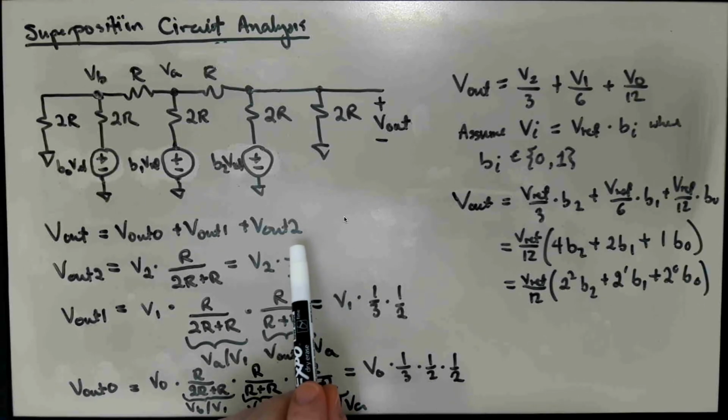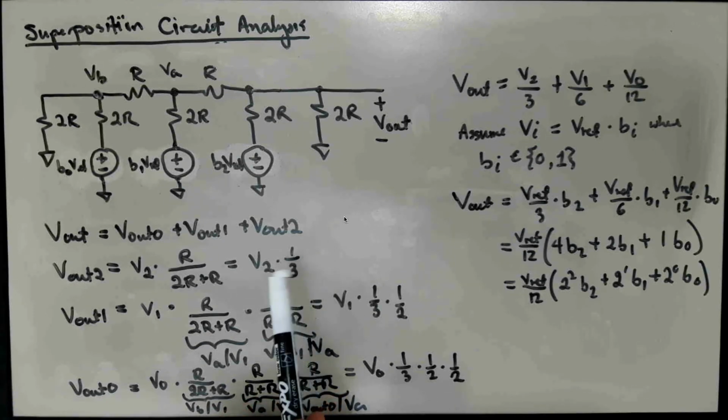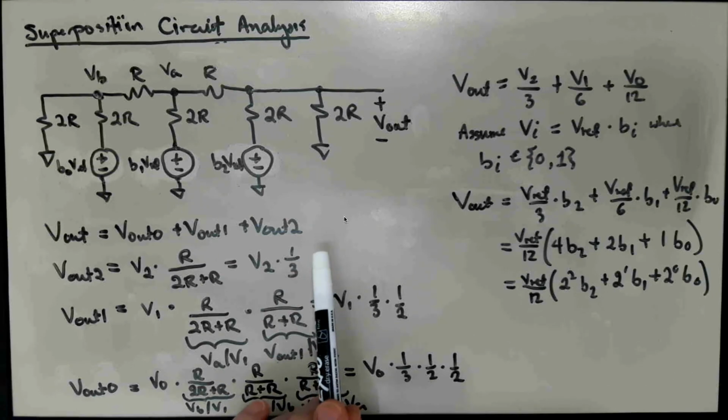You need matching within 1 part in 2 to the n to really make a good monotonic linear digital to analog converter. And 0.1% is about 1 over 2 to the 10th. So much above 10 bits, unless you've got some really super well matched resistors, is probably pie in the sky with this approach.